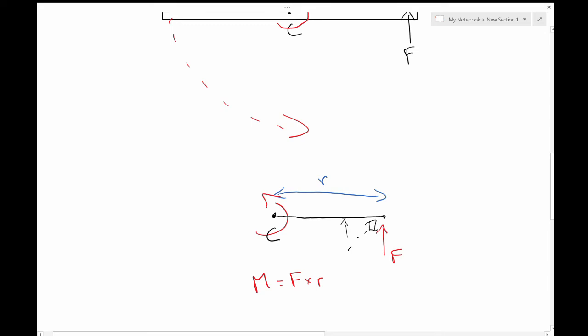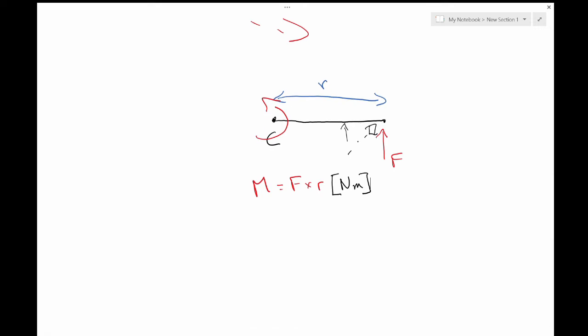And the moment here is going to give us units of Newton meters, which I've always found kind of confusing, because if you've taken some physics, you'll know that Newton meters is also the unit for energy, joules. And it seems weird that we'd be talking about this rotational force, but it's measured in joules. We can get around that through an explanation that I quite like, which is that Newton meters isn't really strictly correct. It's actually the rotational force that is measured in Newton meters per radian.